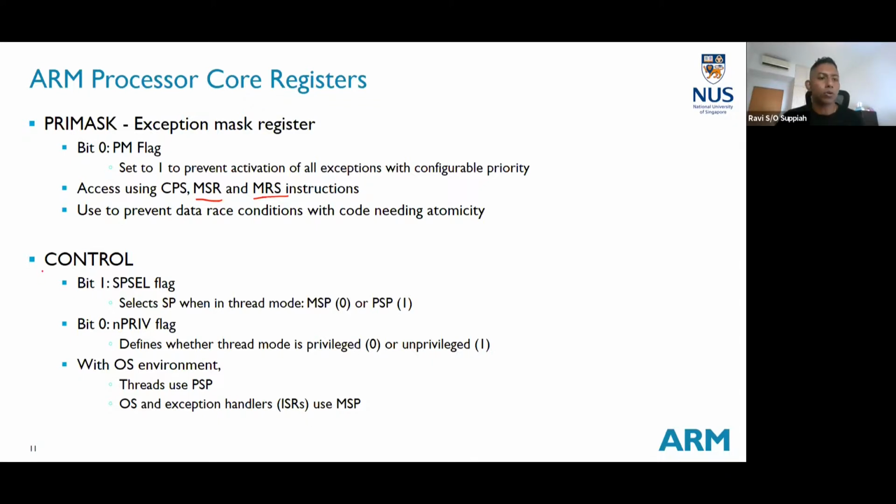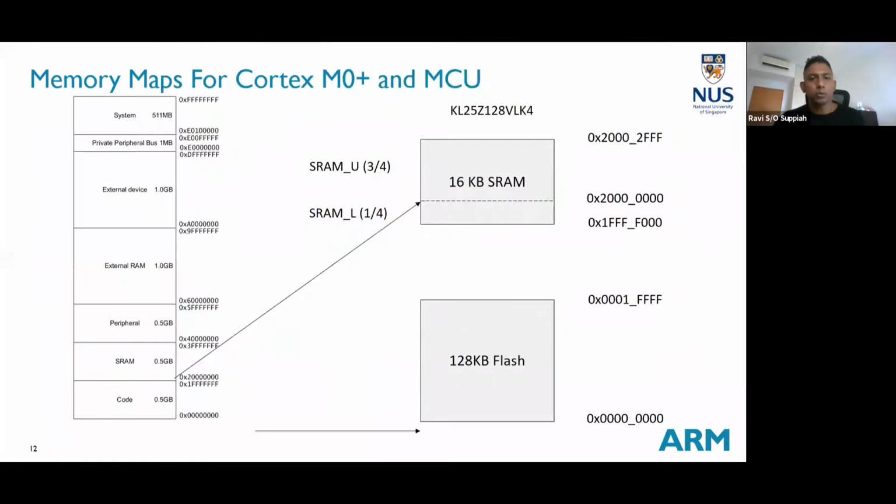In terms of setting or selecting the stack pointer, privilege mode, and so on, there is also another register known as the control register. For us, we will not be touching any of these registers, because we will leave them as default. When the OS is loaded, the default boot up code will already configure it in the correct setting for us. This is just to let you know that these registers are there for us to use.